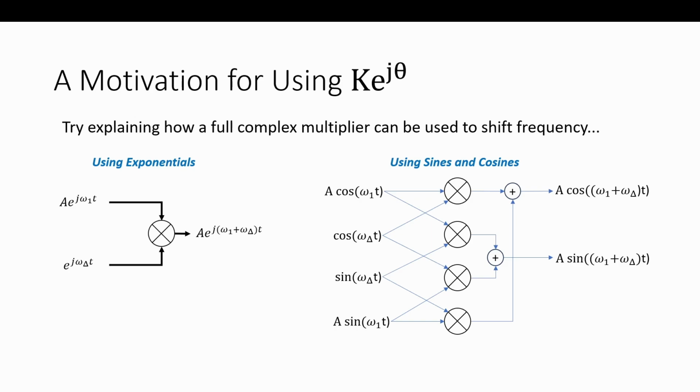So at this point, when I say magnitude A, e to the j omega 1 t, I want you to visualize, okay, it's a single spinning phasor at frequency omega 1, right? Is it a positive or negative frequency? Not both. If omega 1 is positive, it's a single spinning phasor. So the cosine has two tones. This is one tone. Where would you see it on the spectrum? On the positive side, omega 1. A single impulse there at omega 1.